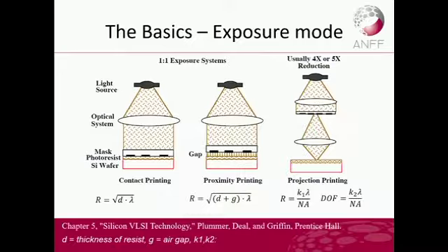That's why these days, at our lab scale, we can use this sort of contact printing with a resist thickness of about 1 micron all the way to 100 micron. However, in industry these days, because you're only making 20 nanometer features, your resist films are now routinely less than 50 nanometers, and some resist films are now just under 20 nanometers.